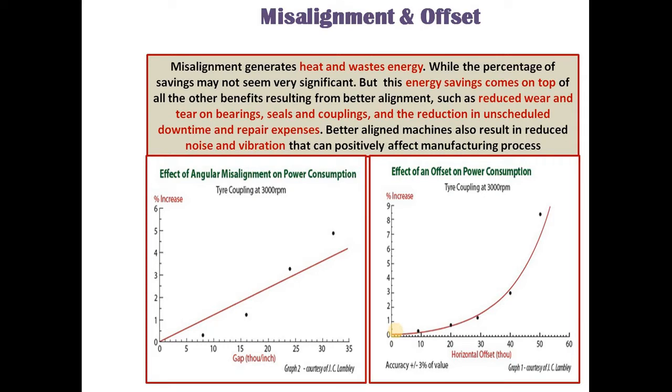If you allow this misalignment, then there will be wear and tear of the bearing, there will be wear and tear of the mechanical seals, bearing seals, coupling may get damaged, and there will be unscheduled downtime. You can reduce this unscheduled downtime if you do alignment properly.